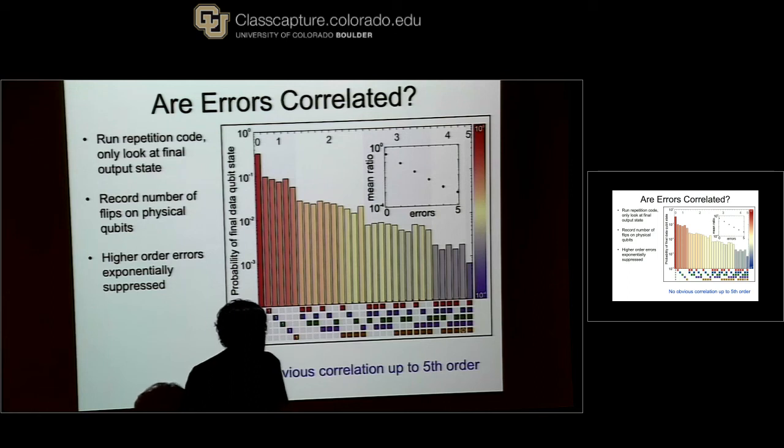And there's a lot to test at that level, for the error correction and whether it's working right. So we have our work cut out to do that and maybe do some other algorithms. But to go to the million, we'll have to somehow put the control electronics cold to be able to connect all those wires. And although we have general ideas how to do that with cold CMOS or Josephson junction logic or something, I'll be honest and say we really don't know how to do that yet. And that's something we're going to work on in the next 5 to 10 years to figure out how to do that.